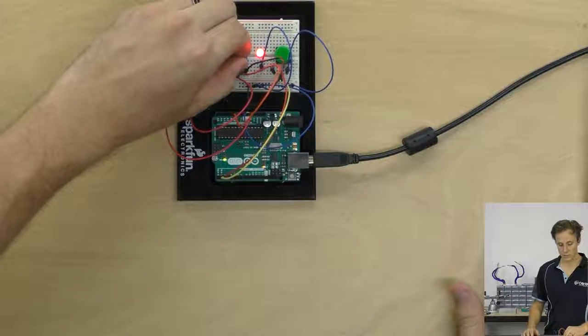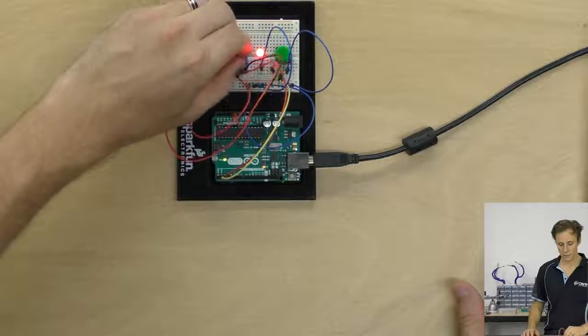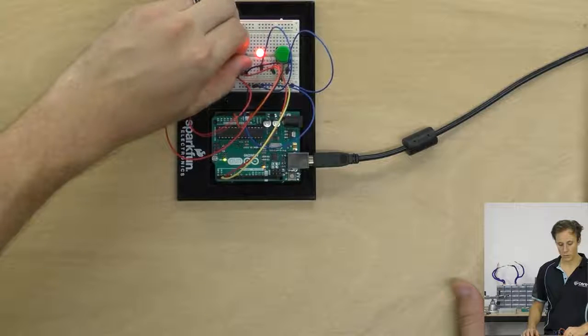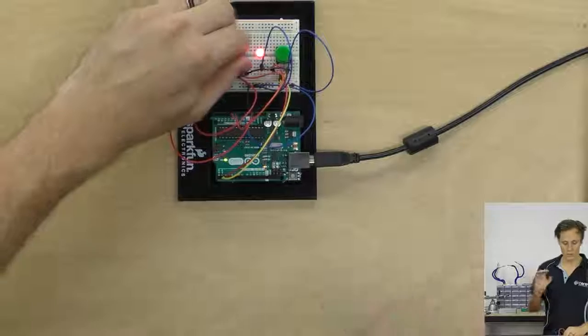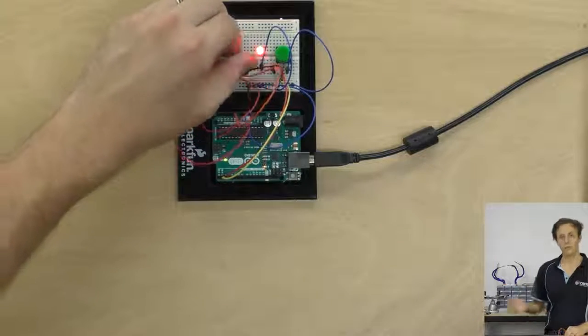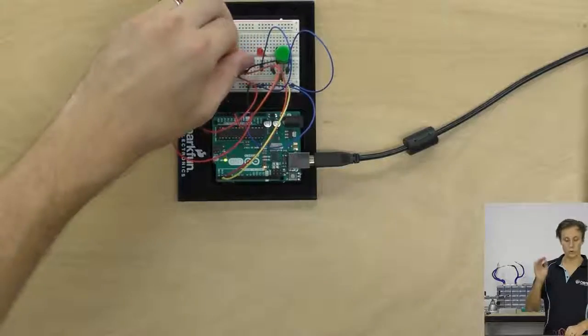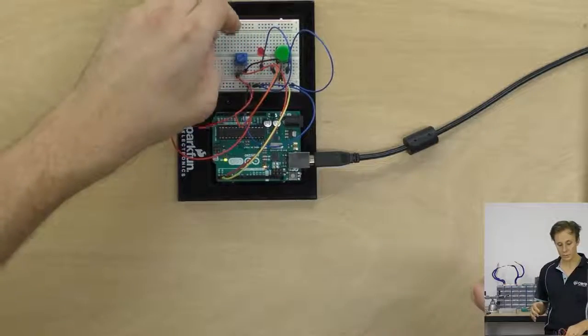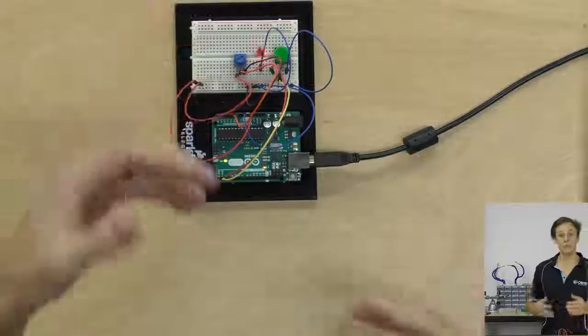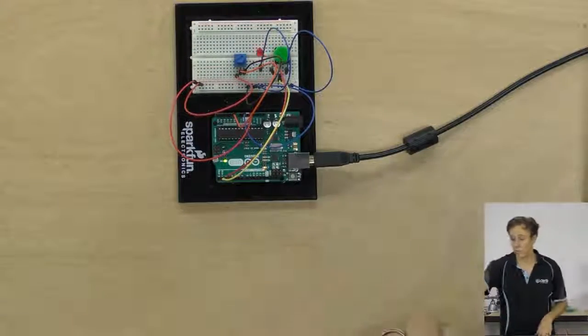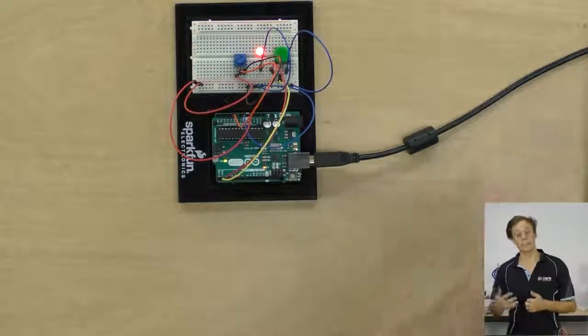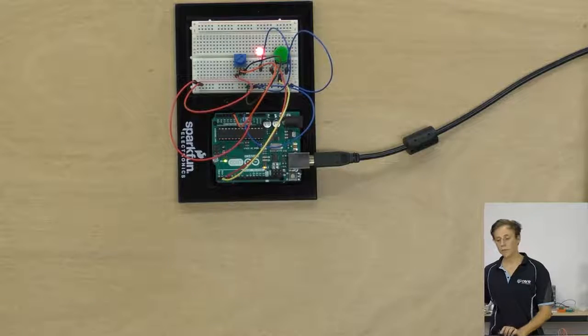And as we slow it down, you can see that delay happening. The blink rate all the way until 1 second on, 1 second off, and so on and so forth. And that is the blink rate. So you can see when we turn it all the way there, we change it rapidly, it takes a second or so to adjust, and that's because of that delay between when it reads the next value. So that's controlling the blink rate.